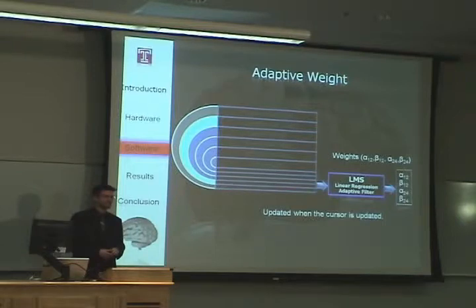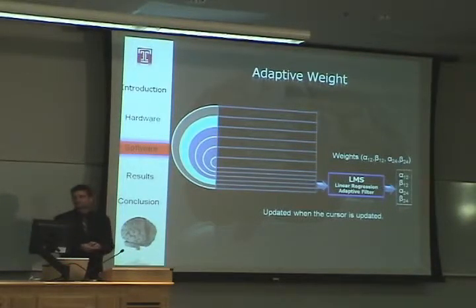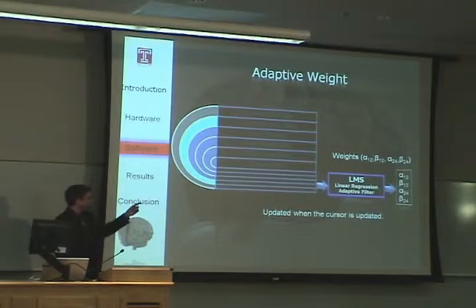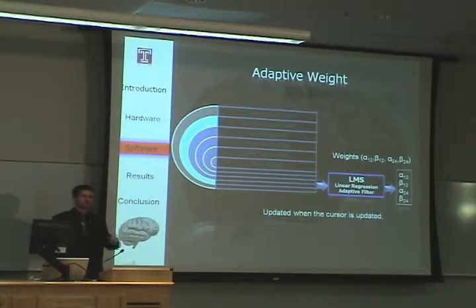I usually use it in order to find the direction of best fit for a line of data that's scattered around. Once the least mean square algorithm is done, it ends up spitting out four weighted values that are going to affect the 12 and 24 hertz frequencies that we saw back in the first slide.